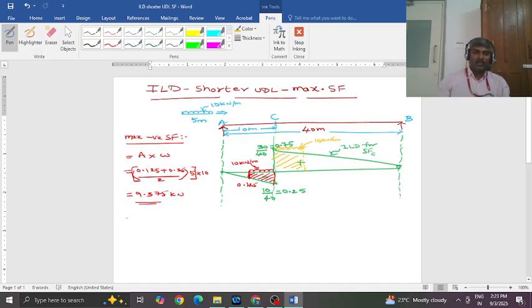So now work out for maximum shear force at C. Okay. So similar formula holds good again. The area multiplied by the load value. Area is again the two parallel sides. So this ordinate here works out to be 0.625 from similar triangles again.